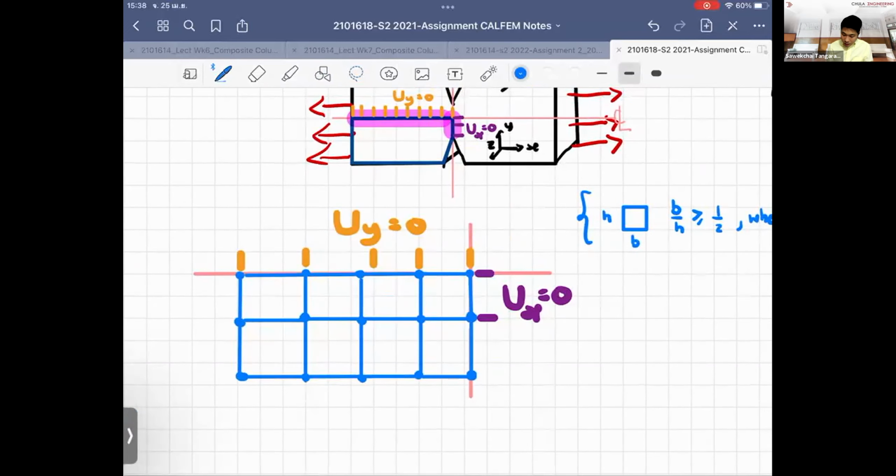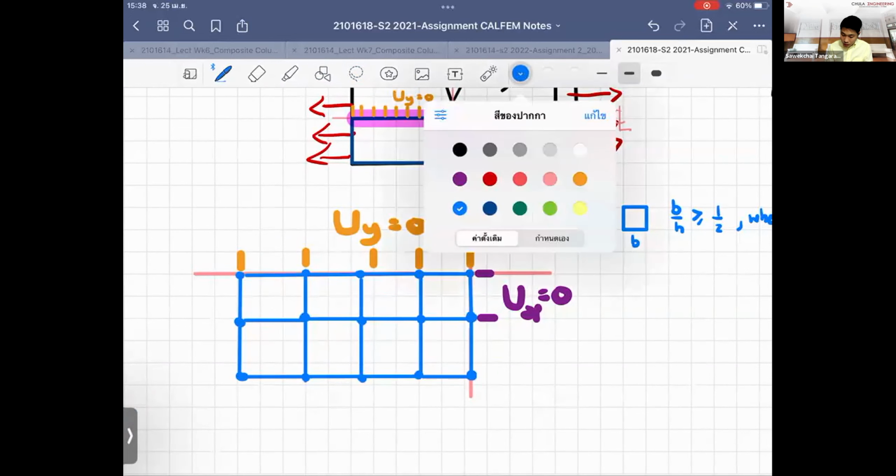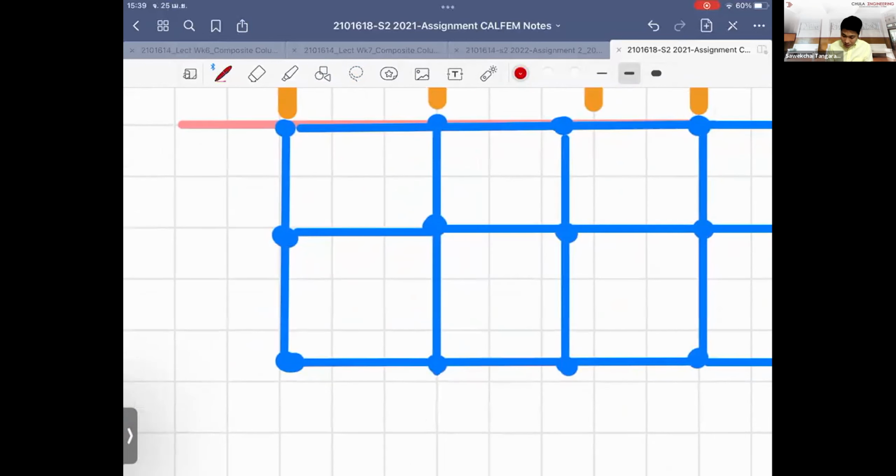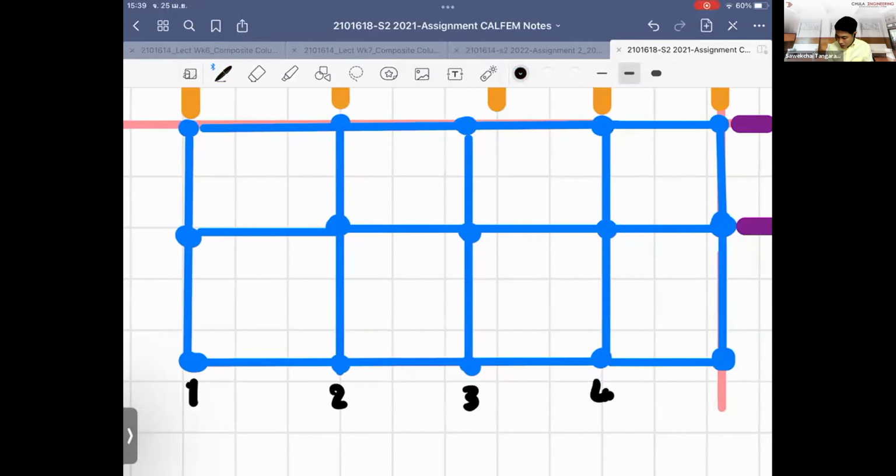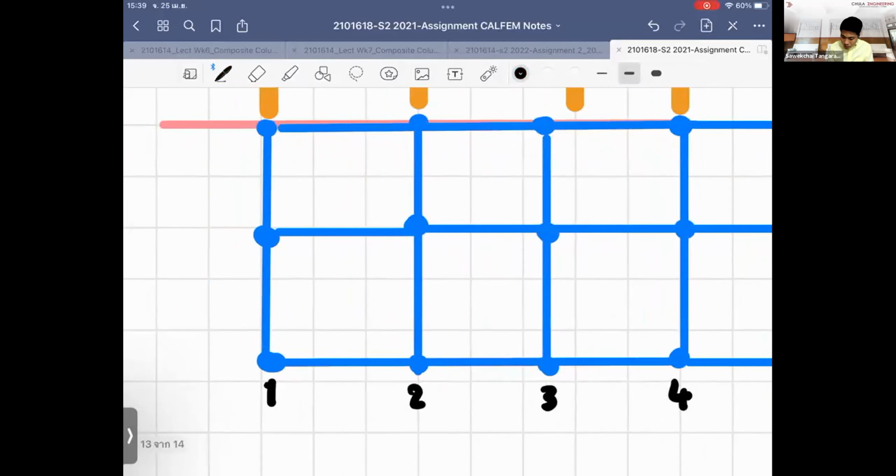And we have already allocated what is called the boundary conditions. What you do next is put in the degrees of freedom. The rest is similar to what you did before: you allocate the node numbers. I normally put them in order, starting from the rows, because later on I can see the series of them.